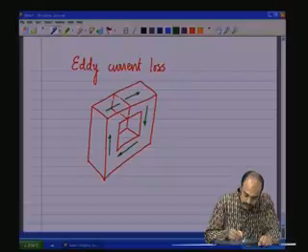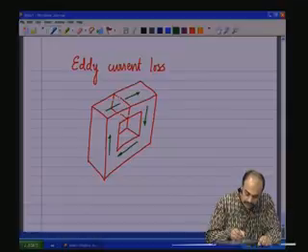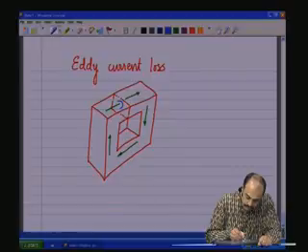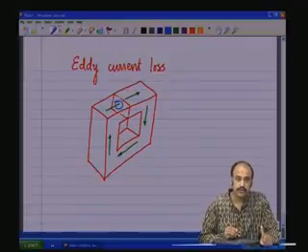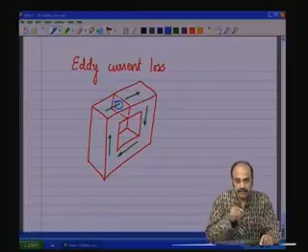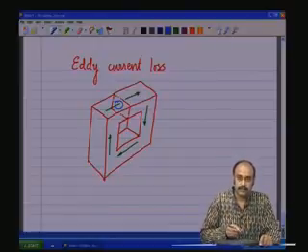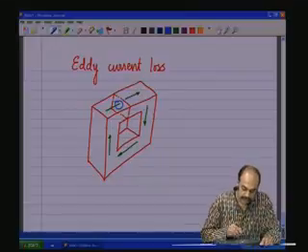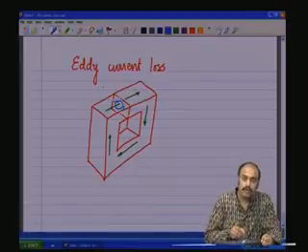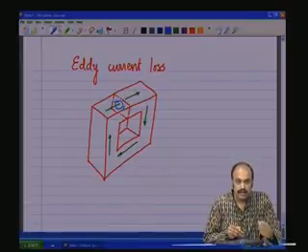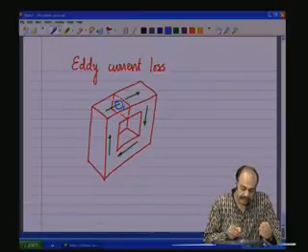So, as the flux is going through this core, of course, that is due to a magnetic field intensity, there is going to be a current loop like that. Because we saw that the converse of the Ampere's law is also true. If there is a current in the conductor, there is a flux around the conductor. If there is a flux around the conductor, there has to be current through the conductor. Now, these currents I are going to produce I square loss in the core material. This causes a loss which is unrecoverable, and that is called the eddy current loss.